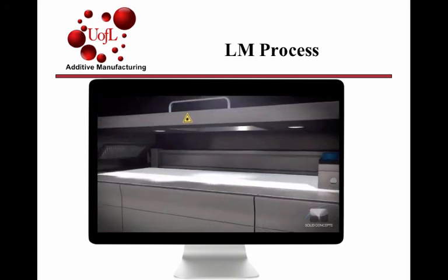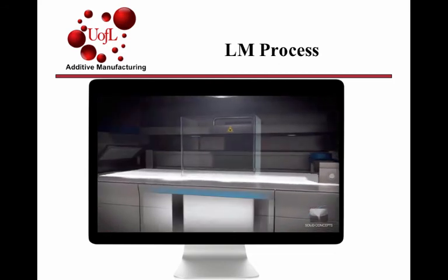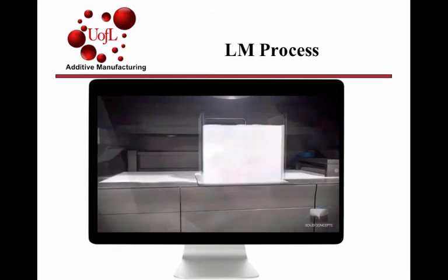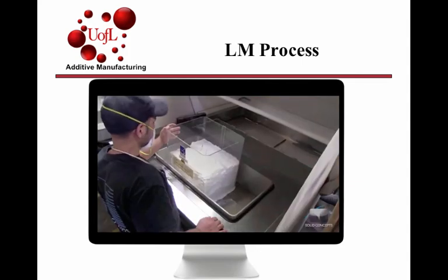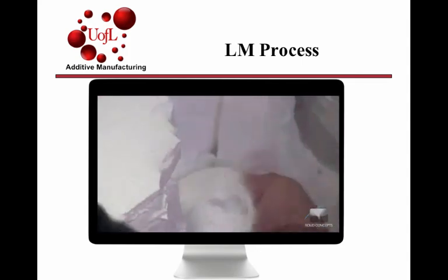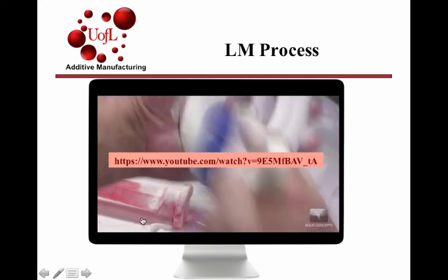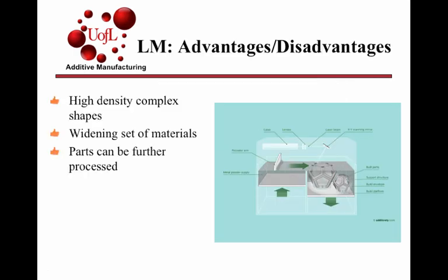As SLS parts are built, they are encompassed by unsintered powder, which provides supplemental strength and eliminates the need for support structures. Complex designs and assemblies, once thought impossible, are now being redesigned with SLS as cost-effective integrated structures. More details can be found in this YouTube link that I've provided for you. So basically you have a bed of polymer powder spread layer by layer, and laser energy is used to fuse the particles. You can make high density complex shapes.